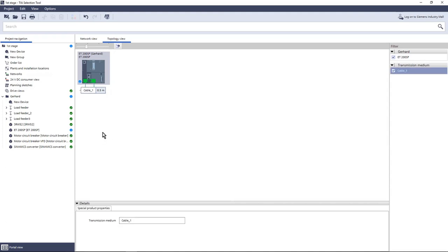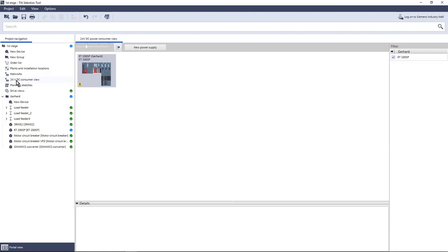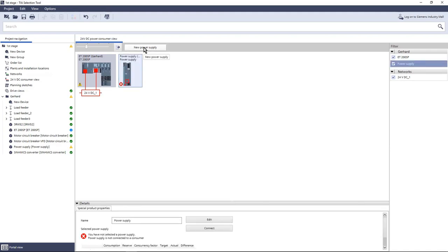Good. Now the other thing that I want to show you is actually after we have selected this, we go to networks. You mentioned already Profinet. So basically here, I will just connect the modules where I need. So as you can see, it's a topology view. Of course, we only have one CPU. So basically, if you want to interconnect the switches, you can also do them. And you can start creating by applying the connector. And once again, the tool will help you out defining how the cables and lengths will be. Okay,